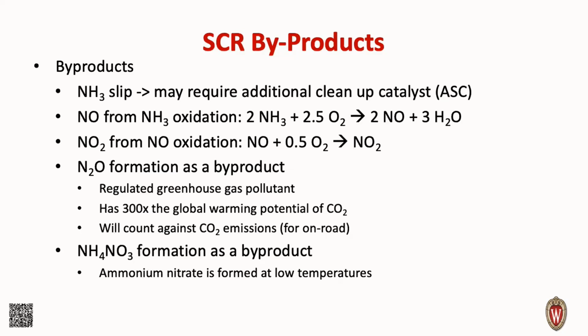And then the other thing that we sometimes worry about is ammonium nitrate formed as a byproduct, which can form at low temperatures, and then we can crystallize that and be in the exhaust. So these are things that could happen if we don't control our SCR process well.